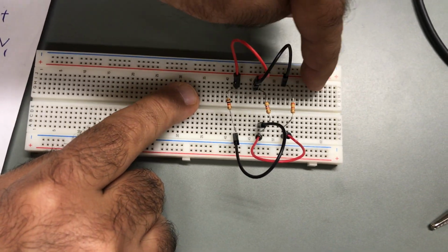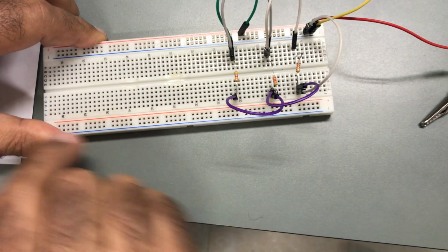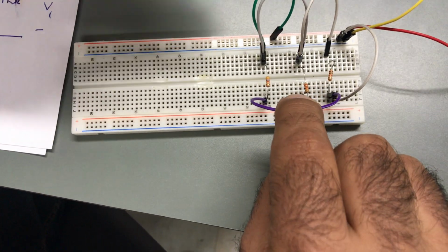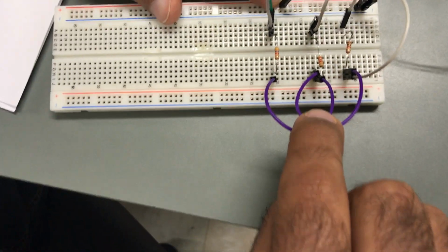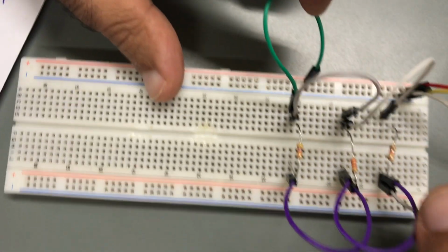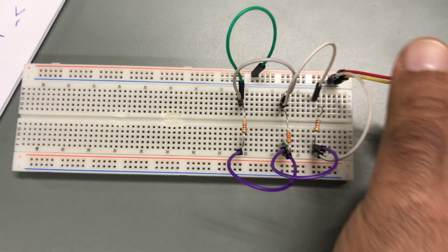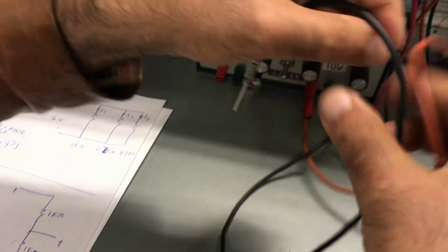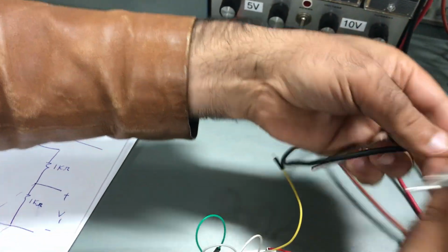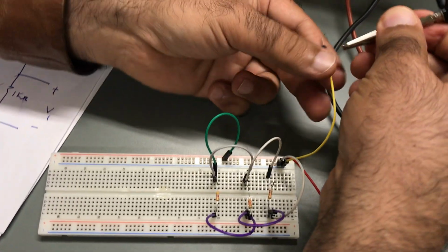Then my power supply will feed these resistors, so I will connect this node to the power supply positive and this node to the power supply negative. And this is what I did here. So these are 3 resistors. These are the same bottom nodes and these are the same top nodes. I connected this node to the positive terminal and this node to the negative terminal of the power supply. Then I'll feed it 6 volts, so the power supply here will be 6 volts. I'll feed positive to positive and negative to negative.